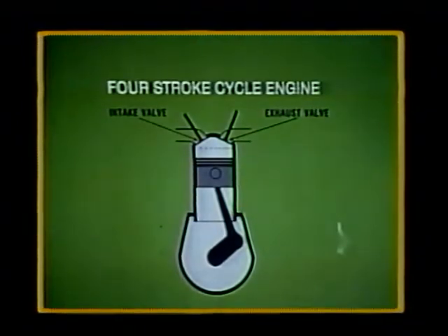The four-stroke cycle engine was developed and became the one used in aircraft due to the inefficiency of two-stroke cycle engines and the difficulty of cooling caused by its firing on every stroke. In the four-stroke cycle engine, 2 valves are timed to open and close at specific crankshaft positions. This allows the fuel-air mixture to enter the cylinder and the burned gases to leave it.